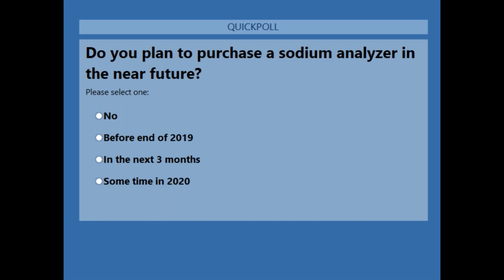It's a very good question. It's not necessary. Can they do that? Yes. The risk they run is the potential error making very low ppb sodium standards, such as a 10 and 100, is much greater than when making a 100 and 1000 or 200 and 2000 ppb standard. So you have greater risk of errors being introduced through the calibration process when using those much lower standard concentrations. And also, since it's linear, it's not necessary. You get very accurate sodium measurements at the levels David referenced when you calibrate with the 100 and 1000 and even the 200 and 2000 ppb standards.